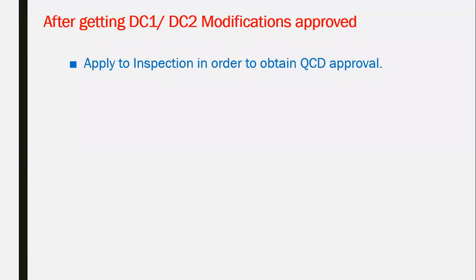Even during the inspections, they will take a tour within the building, and they will check where the assembly point is indicated, where the exits and the exit signs are, the location of the emergency lighting, and the location of the fire extinguishers. If you have a check valve above a false ceiling, you should have an access panel or hatch panel within the false ceiling, and it should be indicated with a label saying this is a check valve or access for the zone valve, etc.